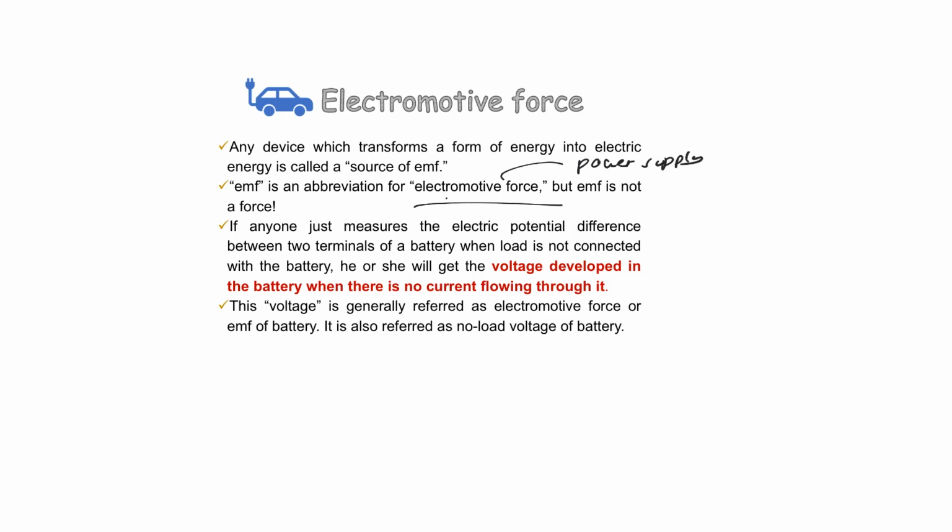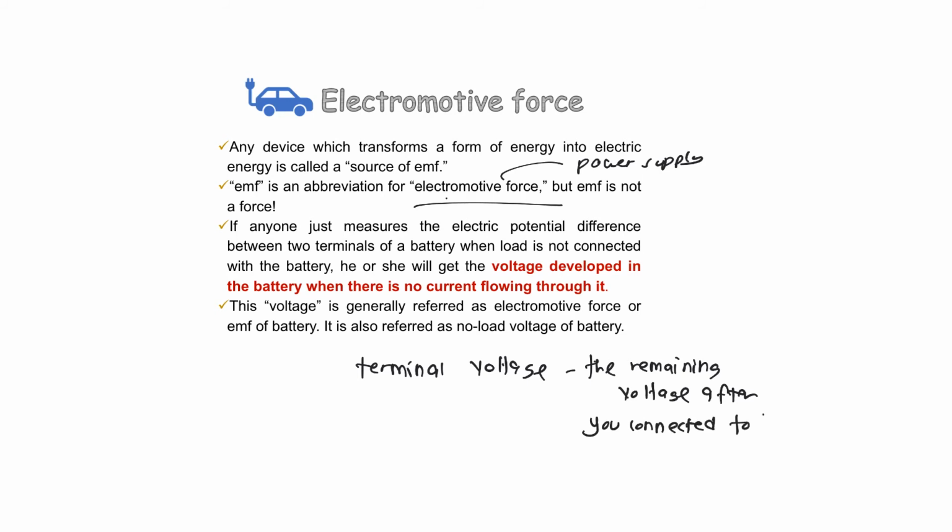That means you haven't connected to the circuit, and that is going to be your EMF. Once you connect to the circuit, if the power supply has internal resistance, then we call it the terminal voltage. So terminal voltage is the remaining voltage after you connect to the circuit.